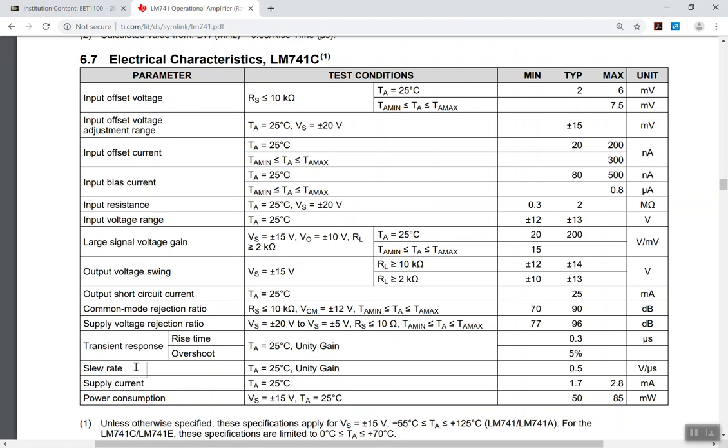And when we say how fast, well, if we have a high frequency signal, that means the voltage in a high frequency signal is changing rapidly. And so if it's high frequency and we don't have a high enough slew rate, the op-amp won't be sufficient.